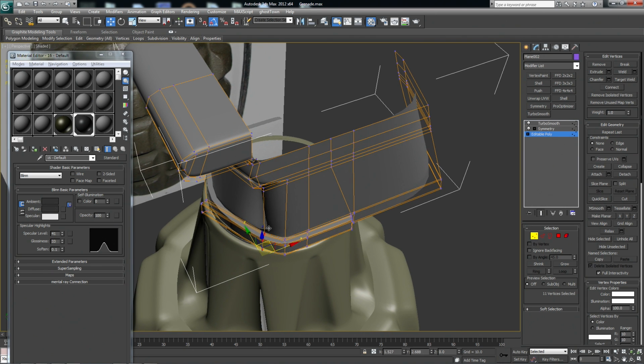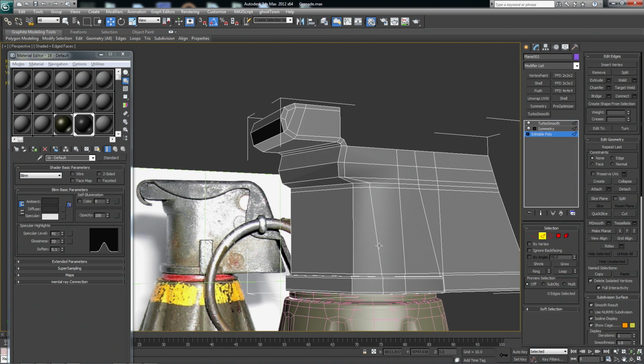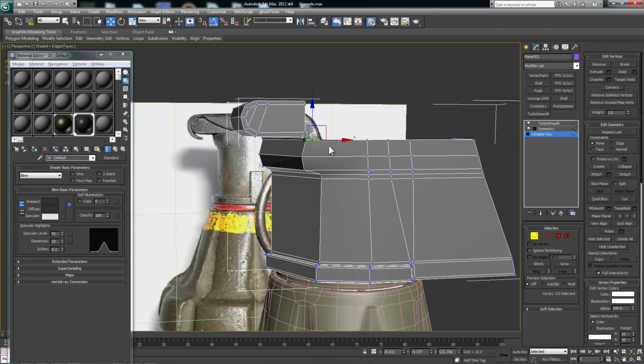Next, I'm going to manually smooth this bottom corner out because some of the new supporting edges are squaring it off. After some unsuccessful tweaking, I realized that this vertical edge is causing the main form to appear harder than in the reference. I can select the bottom half that is causing the issue and hit Control Backspace to remove it. Now we can manually cut from this unresolved vert in a curved downward direction so that its surface smooths more gradually than before.